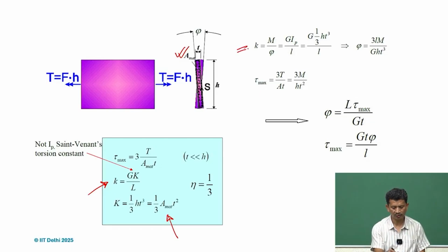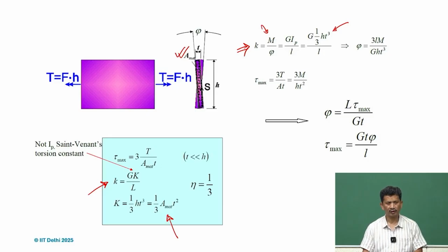And then if we talk about the rotational stiffness, where we have to apply the torsional moment M and the associated deflection phi, this will come into the picture. So it's a to the power q, and that's how we realize that it's torsionally not rigid and it's very compliant. So whenever we are using this kind of element in the design, we have to be aware of that. And later we realize that the sheets, many times they are used for compliance, not for stiffness.